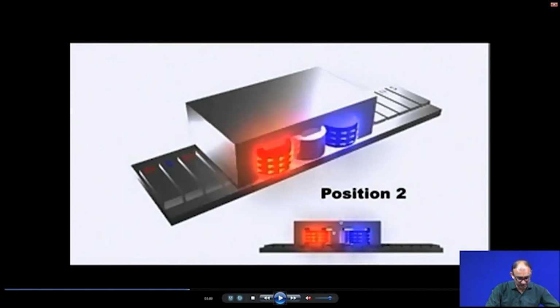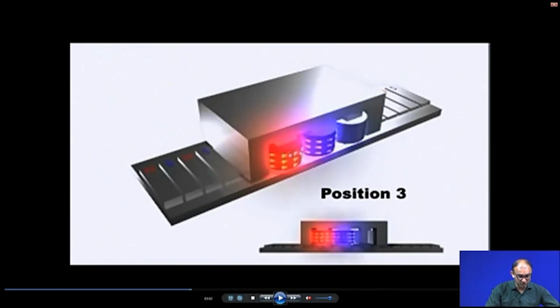Now, you can see that there is a switching over between the two. So, now the middle one is off, and this one becomes negative and positive depending on these polarities. Now it has moved to the second position, and now it is in the third position. It depends on how frequently you are changing the position of the poles. The faster you change this, the faster you can get the movement in the linear direction.